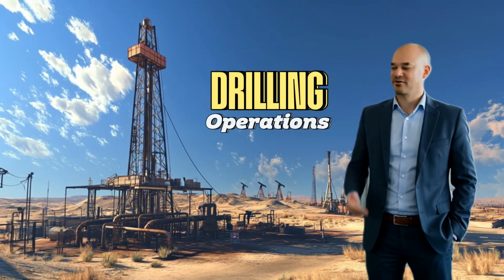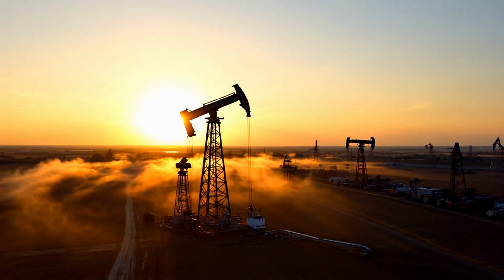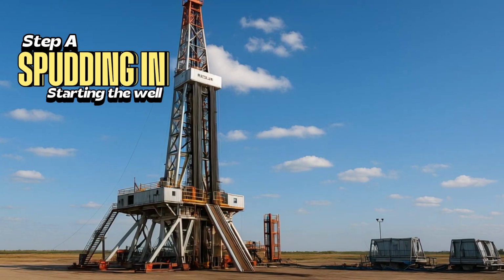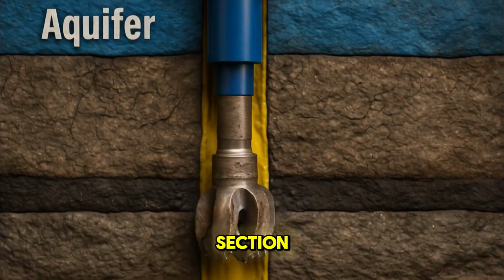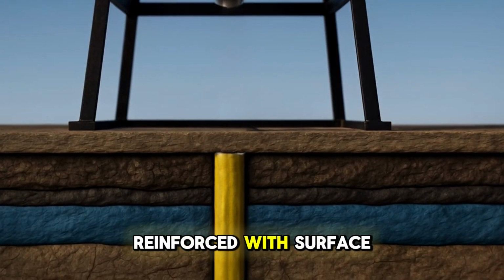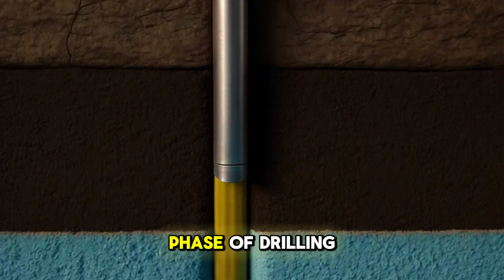Now let's deep dive on the drilling phase. Step-by-step process in oil and gas operations. Step A, spudding in, starting the well. We begin by drilling a shallow section known as the conductor hole. This section is reinforced with surface casing to prevent the hole from collapsing during the initial phase of drilling.